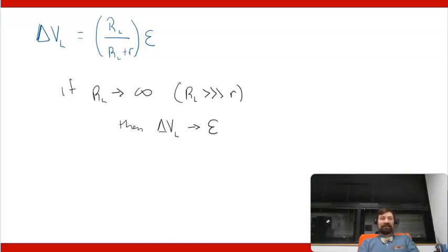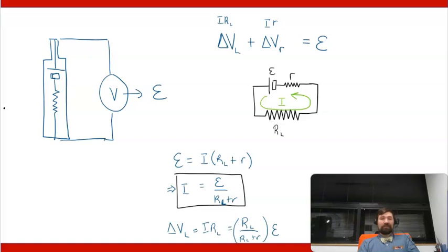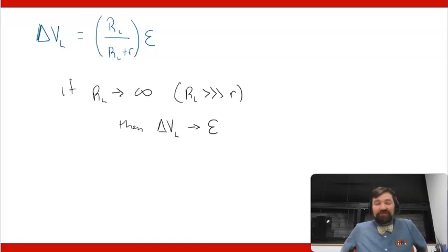So again, that's why this EMF is equivalent to the open terminal voltage, assuming that this has a resistance of, let's say, like 10 megaohms or something like that. It's some really big number, like infinity. Okay, 10 is not infinity, but this, we could say, approaches infinity. And we can get an approximation for what that means by using like 10 million ohms versus an internal resistance of 10 ohms or something. Okay, so that's basically how this thing behaves.